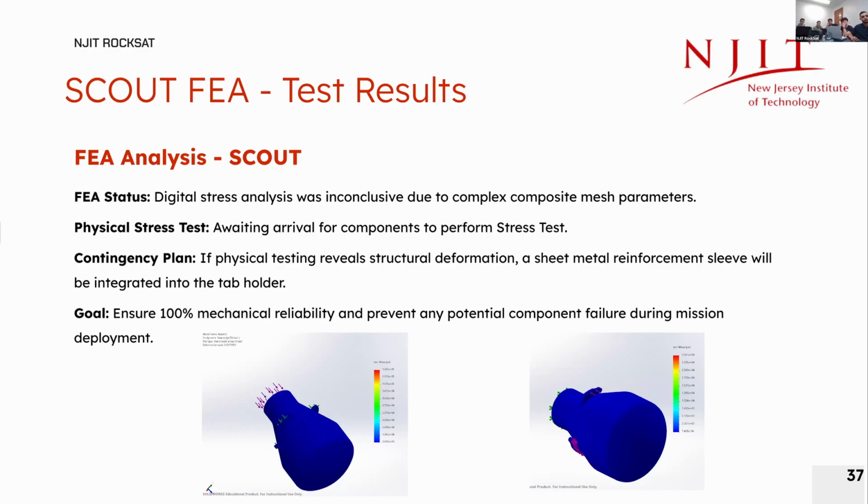So the plan is that we print the Scout and we just do a physical test with the spring force, which should be 20 pounds. And if we see any deformation or any cracking or anything like that, then we would put aluminum sleeves within those notches.